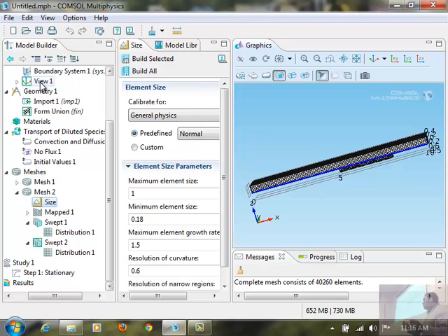So this selection is just one face? Is it including the curved face, or is it just the whole rectangle? Including the curved face. In COMSOL, it's not just one face, it's all the faces on the same plane. That's why I said let's count how many there are. I thought there should be 26, but it looks like there are more. It depends on how it broke that curve. We have a center line also, which makes it 13 multiplied by 2, so I expected at least 26 faces. If it had more than that, some internal boundaries may be split into more than 2.